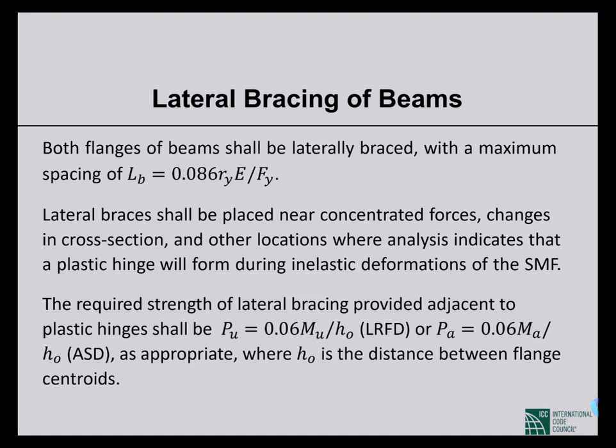Lateral braces shall be placed near concentrated forces, changes in cross-section, and other locations where analysis indicates that a plastic hinge will form during inelastic deformations of the SMF. So usually we do that. We provide lateral braces near concentrated forces or when there is any abrupt change in cross-section.